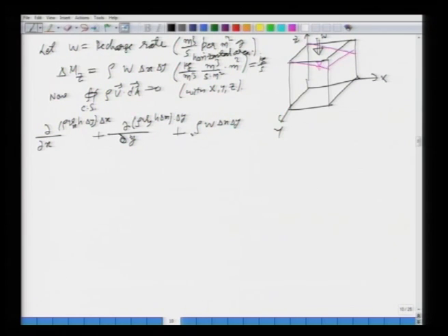All right. So, we have added this in the z direction. All of this should be equal to 0 as per your continuity equation. Okay. Now, we do the same thing, and what is that? We combine this continuity equation with the momentum equation, which is your Darcy's law, and simplify. I am not going to do that because we have seen it already.